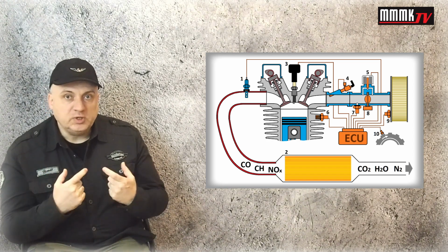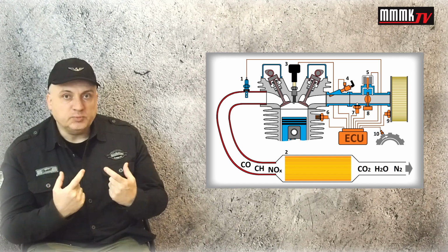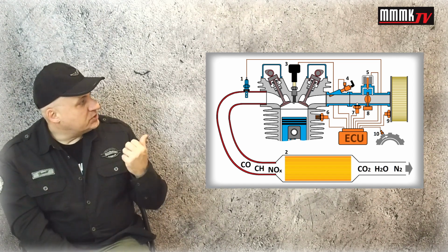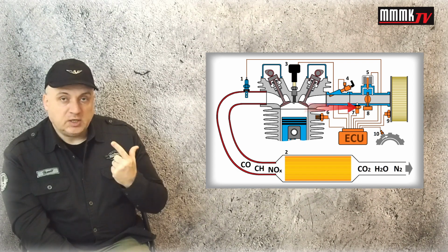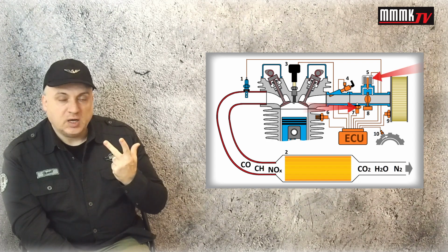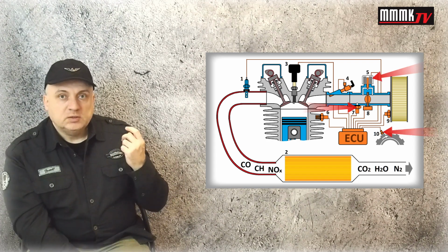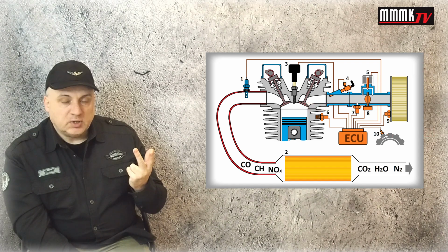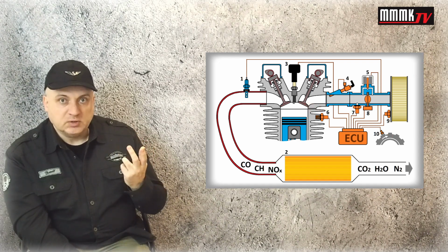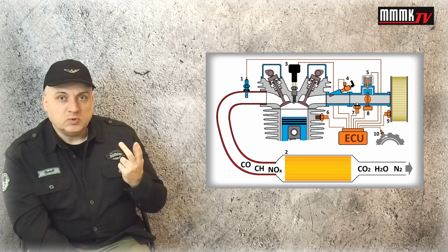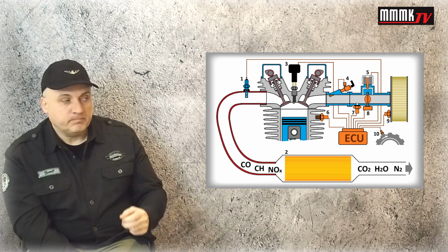There are 3 necessary signals on the input side, one of the most important being the MAP sensor. The second one is TPS, and the third one is RPM. These 3 signals are absolutely necessary and absolutely sufficient to make the injection system work properly.